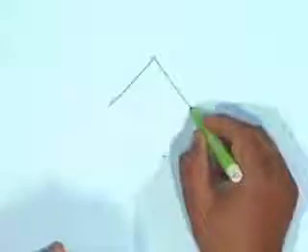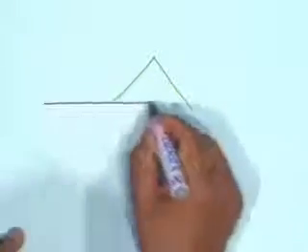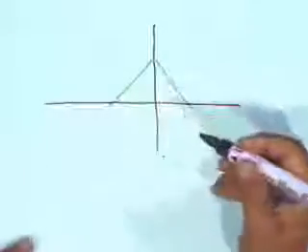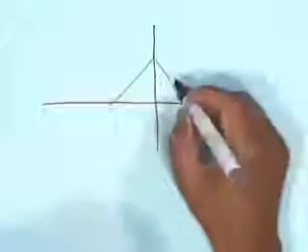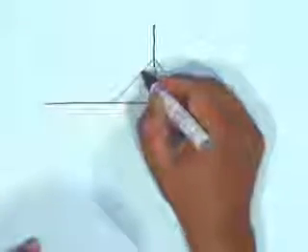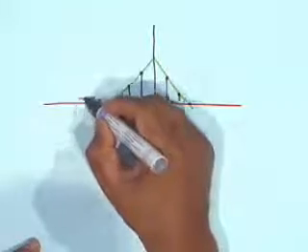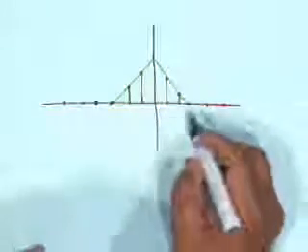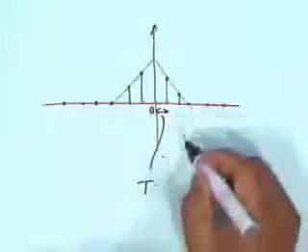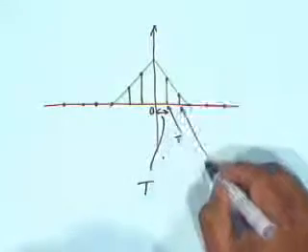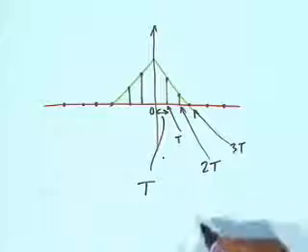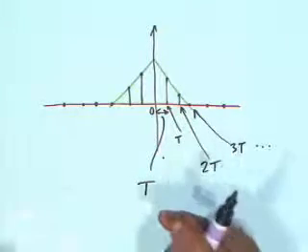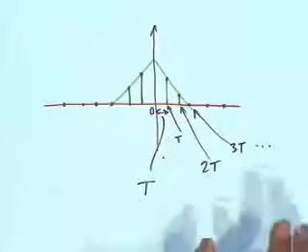is like this. Suppose we take the same signal again, and let's say we sample uniformly, that is, we have 3 here and let's say 3 here, and uniformly, alright, and let this interval be capital T. Therefore, this will be 0, this is capital T, this is 2T, this is 3T, and so on. Alright. In most of the discrete time signals that we shall talk about in this course, we shall consider uniform samples, that is, uniformly spaced samples.